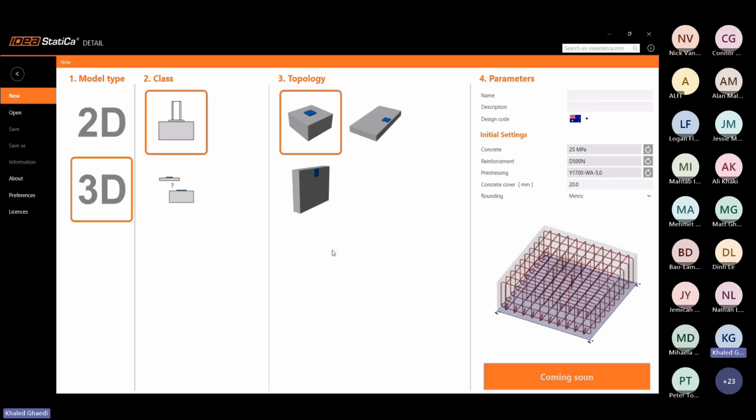Maybe you want to just play with the length of the shear lug. So here, let me just put it as 0.5. This is how you can actually work with the shear lug. And also you have the friction and definitely anchors. In terms of the anchor, you also have the interconnection with the base plate, through the axial force and shear force. And again, you have the options to edit the anchors as well. Just like in 2D detail, you can add the loads at any location of the base plate. You have the type of anchorage, you have the template of the reinforcement, you can put it there, and then after defining the load combination, you can just run the analysis.